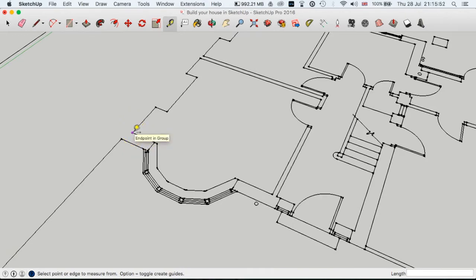And for those of you who don't know, the way to imagine a plan view is if you take a line which is 1 meter above the floor, and if you were to get a chainsaw and chop through your house, you're drawing a picture of what you'd see. Now, you don't need to go into detail. Obviously, don't include things like furniture. You don't need to include the actual makeup of the wall. You just need to have the outline of the wall.